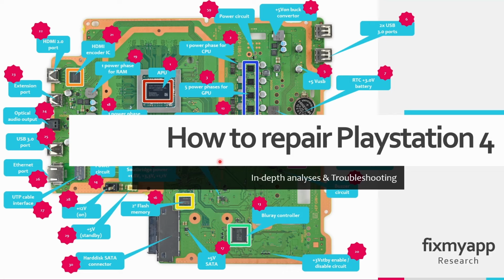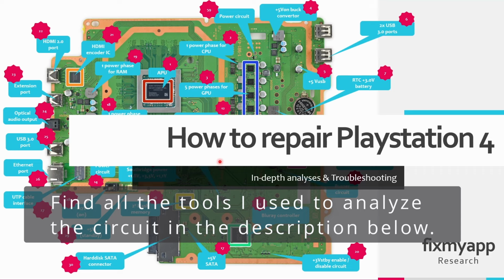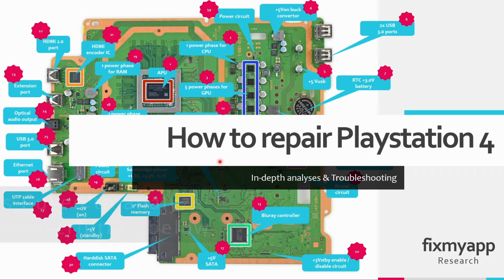Secondly, I will give some general troubleshooting tips for common issues like the Wi-Fi problems, white light of death, the blue light of death and no power behavior. Lastly, I will provide diode measurements for the different components that are used on the mainboard. I will also provide resistance measurements and standby voltages and power on voltages that are being used at the PlayStation 4 Pro.